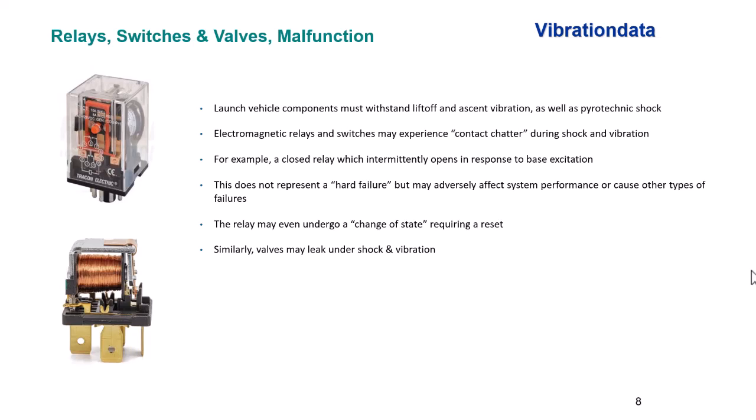A valve that's supposed to be closed may cause a leak of a fluid or gas under shock or vibration. Well, how much, if any, leakage is acceptable? Well, that's something that needs to be thought about, and there's some concern there that we have. So nothing actually breaks, but these components are not operating as designed due to the chatter or the leakage type effects. So we have to be on the lookout for that.